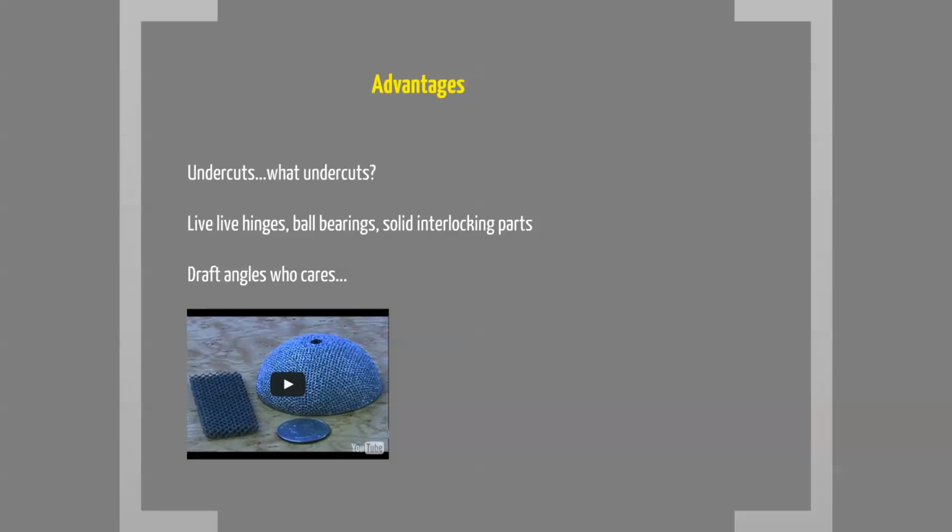And then draft angles, who cares about draft angles, right? Once again, kind of like undercuts, draft angles aren't as much of an issue because you're not pulling the object out of a mold. And so in that sense, draft angles don't matter nearly as much.